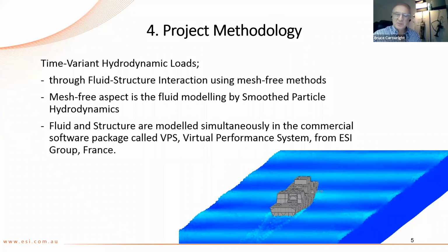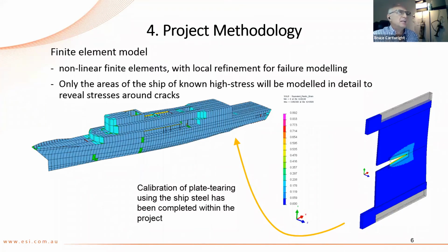And when I say a time step, this is a time marching simulation, so that everything happens in the time domain, and there are very, very small time steps between one step and the next to make sure that all dynamic loads are captured as they propagate from one element to the next. So we're typically talking of time steps of the order of milliseconds or fractions of a millisecond.